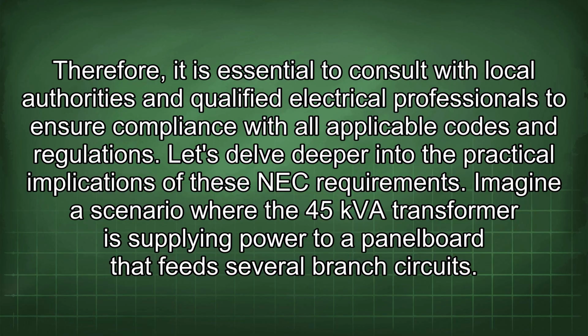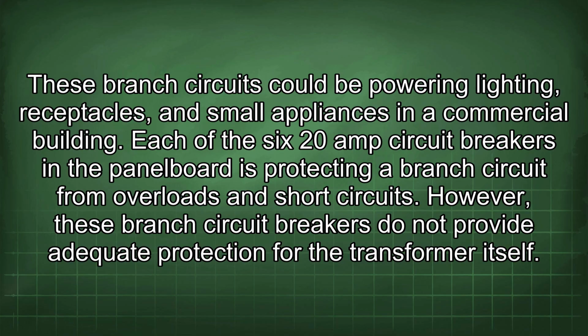Imagine a scenario where the 45 kVA transformer is supplying power to a panel board that feeds several branch circuits. These branch circuits could be powering lighting, receptacles, and small appliances in a commercial building. Each of the 20 amp circuit breakers in the panel board is protecting a branch circuit from overloads and short circuits. However, these branch circuit breakers do not provide adequate protection for the transformer itself.